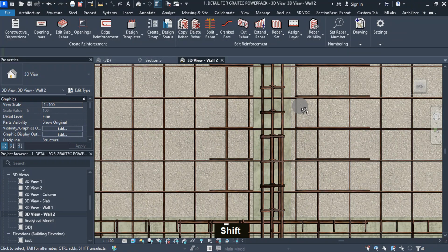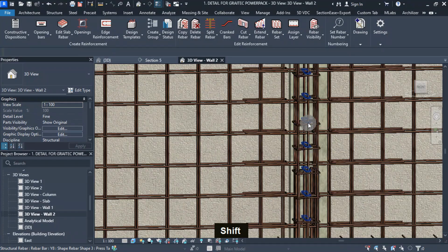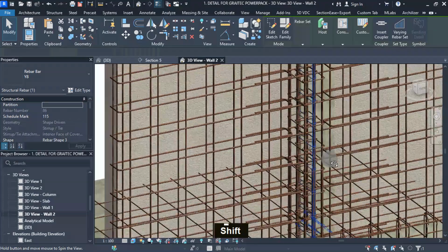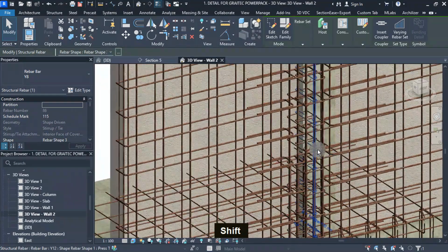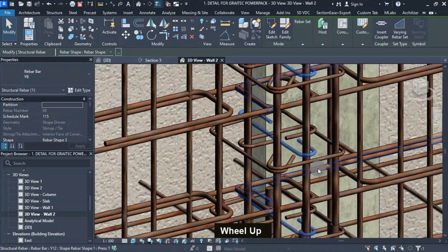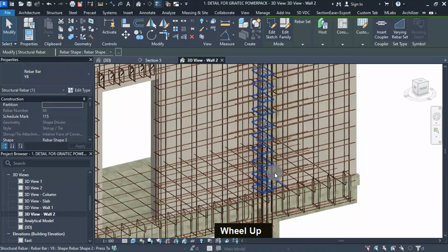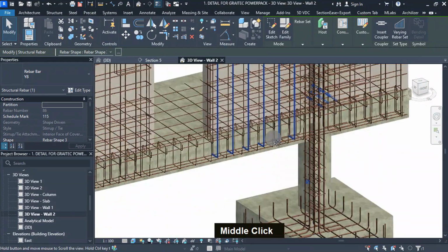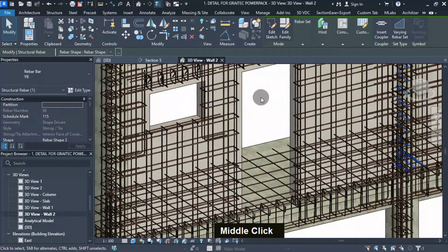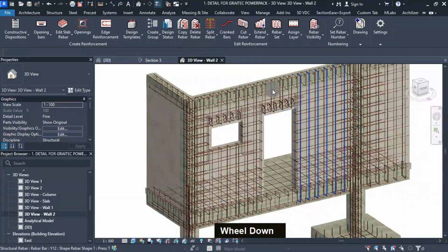I can rotate within the column to view the rebar orientation and the linkage details at the wall edge. This plugin has detailed all bars as defined in the reinforcement assumptions, then by adjusting to the preferred parameters in the main bars and wall linkage commands. The U-shaped edge bars can be modified from the wall linkage bars command. We can proceed to modify the lintel bars using the plugin tools.